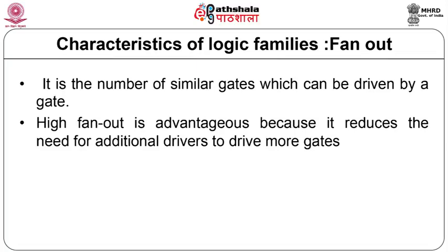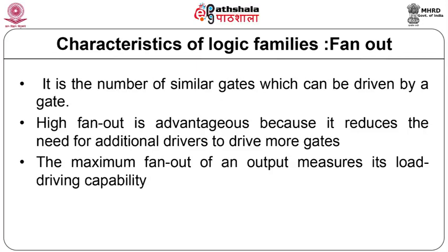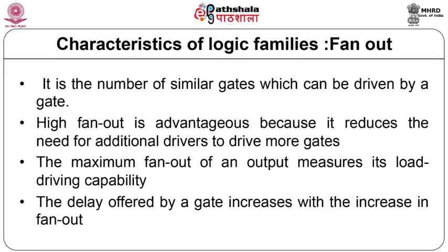High fan-out is advantageous because it reduces the need for additional drivers to drive more gates. The maximum fan-out of an output measures its load driving capability. The delay offered by a gate increases with the increase in fan-out.